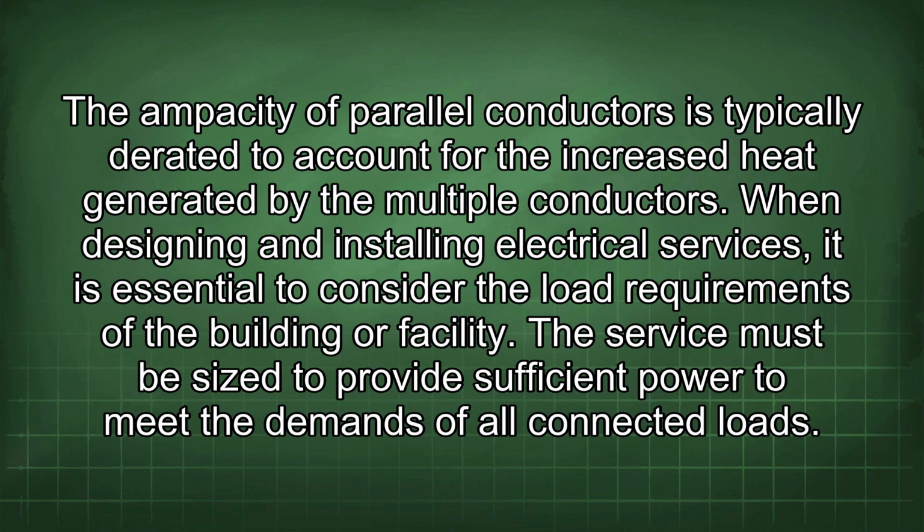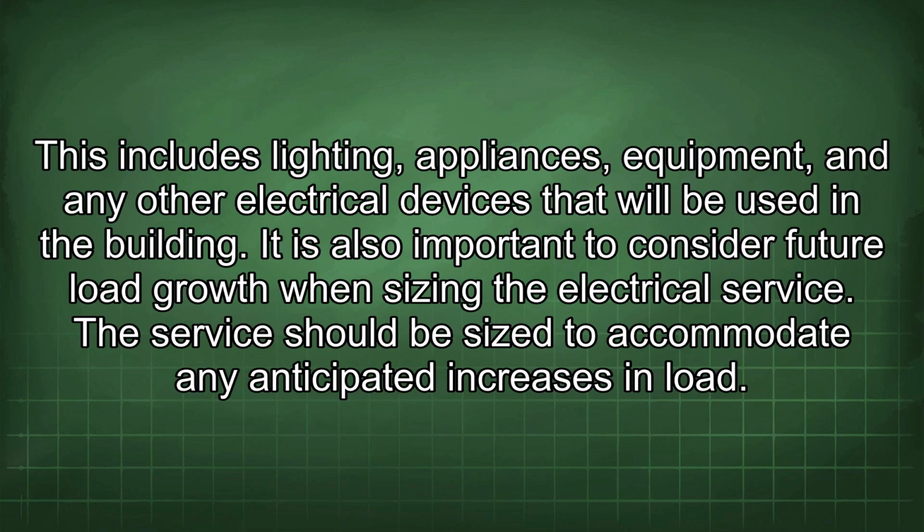When designing and installing electrical services, it is essential to consider the load requirements of the building or facility. The service must be sized to provide sufficient power to meet the demands of all connected loads. This includes lighting, appliances, equipment, and any other electrical devices that will be used in the building. It is also important to consider future load growth when sizing the electrical service. The service should be sized to accommodate any anticipated increases in load.